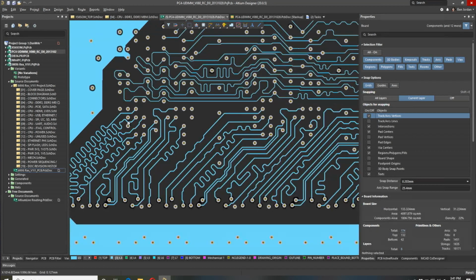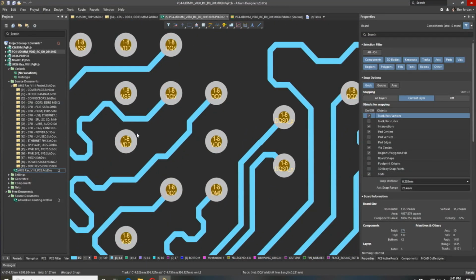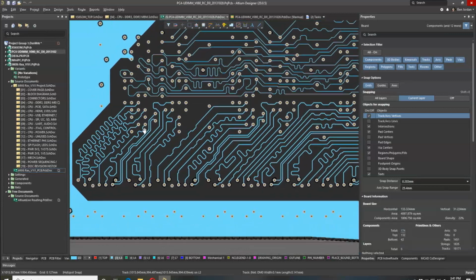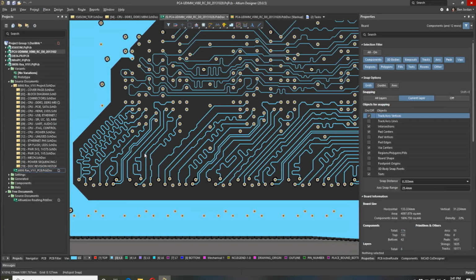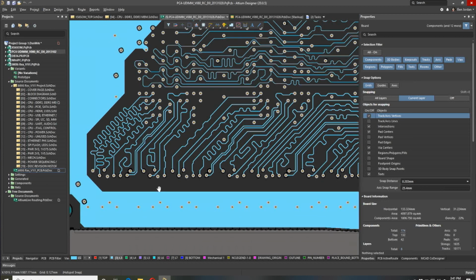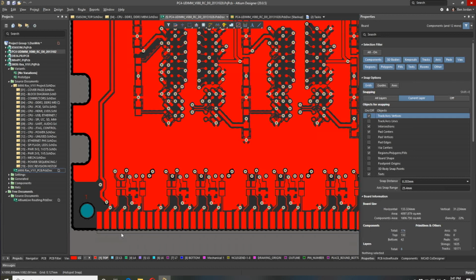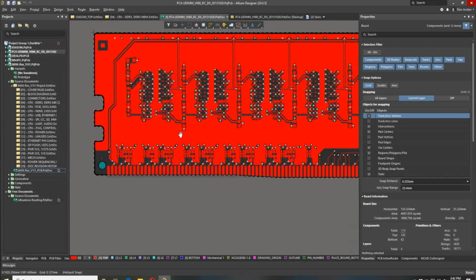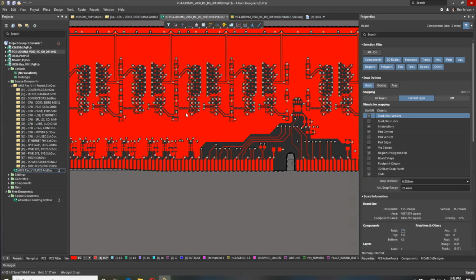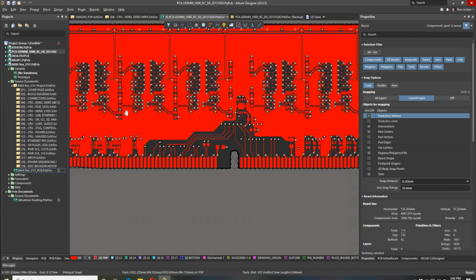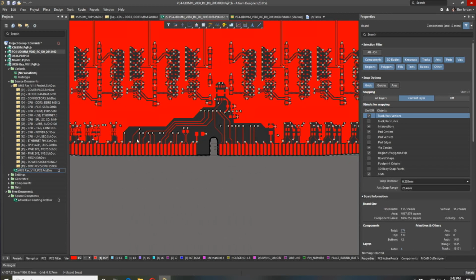And if you look at the signal names, you see they're the DQs. Each chip may have maybe an 8-bit wide chip. I think these are all 8-bit wide. You can get chips in 16, but they're all routed in parallel to give us a 64-bit wide memory device. And so they go straight down through their series terminators to the parallel data bus. These are the series terminators here, these resistor packs. And so we have a direct connection there. So this is a partial parallel topology and partial flyby,